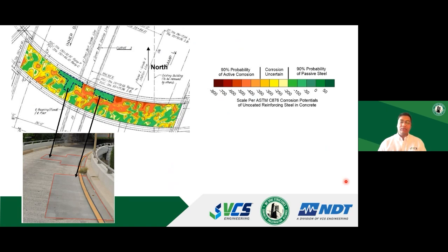So what happens is your anode is now the rebar right outside the repair area, right at the boundary of the repair areas. That's where your new anode is, and that's where the corrosion would happen. Effectively, when you perform patch repairs, if you don't implement any corrosion mitigation solutions, you are forming another potential area of deterioration right outside the patch repair.